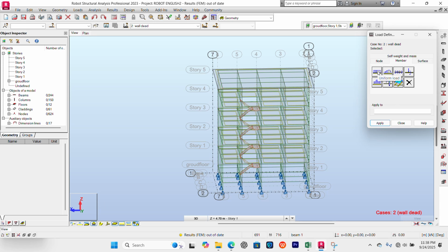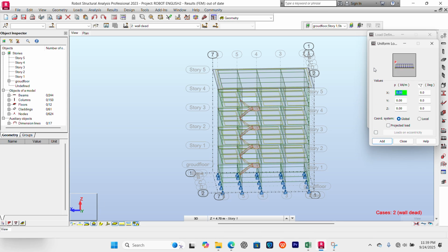For our walls, there are many types of load depending on the shape of the wall that you want to apply, because we have those edges when you look, for example, at the roof pitch, where they usually are block and it goes up like a triangle. There you can decide maybe to apply this other form, trapezoidal load or triangular load. So now click on uniform distributed load. You choose the Z component. You make sure that you are on Z component.